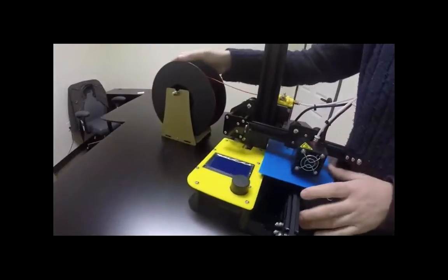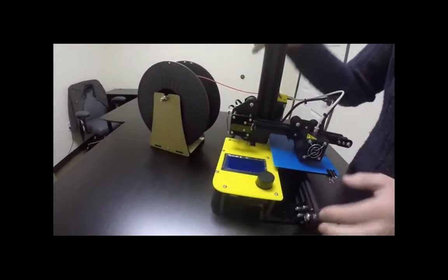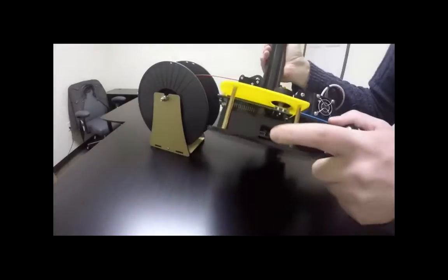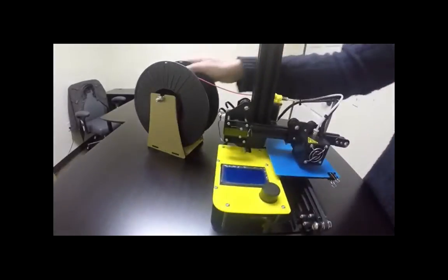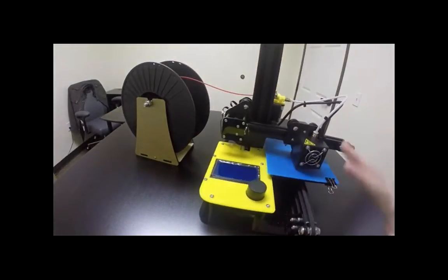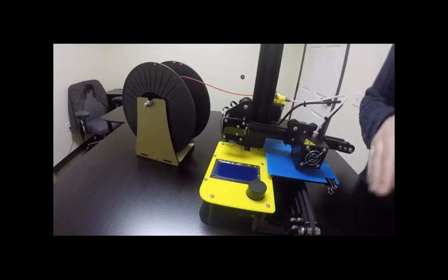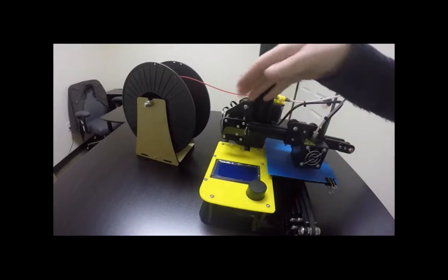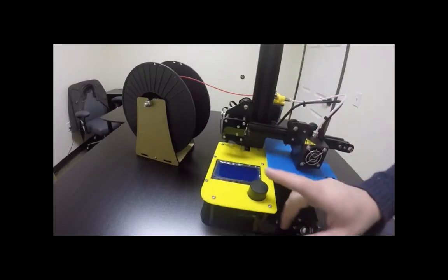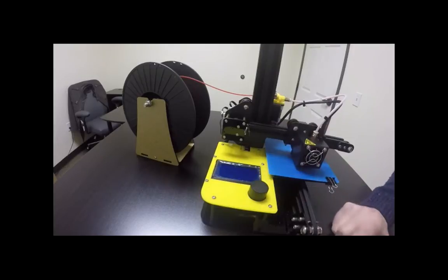Okay, awesome. So now we're going to go ahead and make sure that the SD card is in. So did you guys put the SD card in the front? Okay, awesome. So we're going to heat it up. And this heating up step is how you can also make sure that if something gets clogged, you can work with it. So we're going to heat it up and first load the filament to push it through. So to do that, plug it in and then tap this button right here. And then spin to where it says prepare and then preheat PLA.